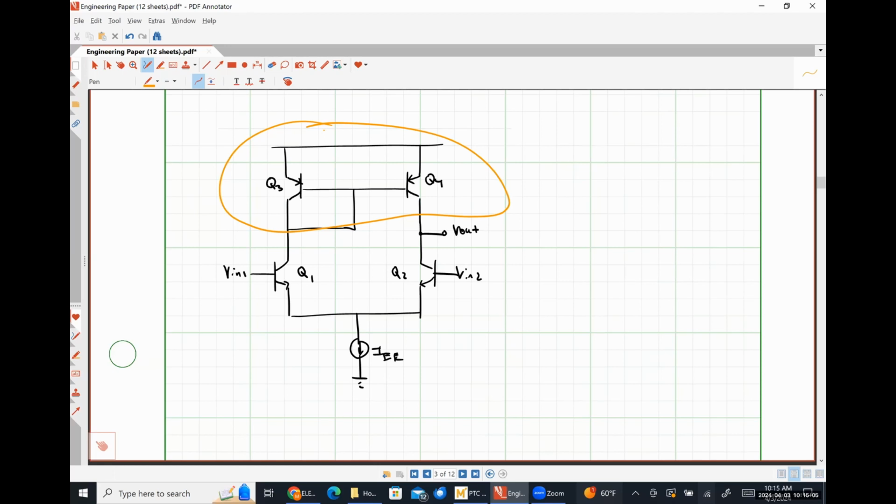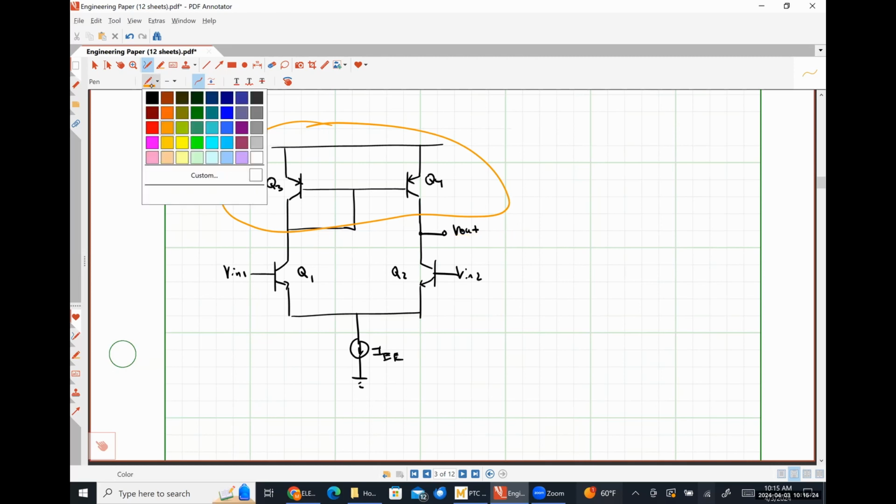And we probably would wind up putting a third stage in that's literally just to increase the voltage swing. It's what's commonly called a push-pull amplifier. And it just helps the output get closer to the supply rails. So that's a single stage amplifier. We might do something like this. I'll just do the second stage here.